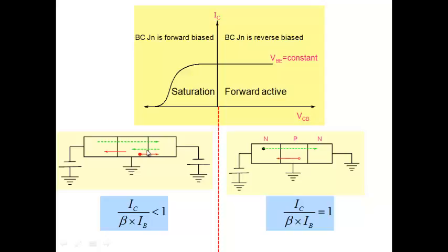So collector base junction is larger, it has lesser doping, and it has higher currents associated with it. So when you are saying when does this begin to occur, maybe it begins to occur when collector base voltage is, let's say, 0.5. It depends on how the transistor is constructed. But it's lower than the base emitter voltage. Okay, so this starts falling. We'll show you transistor characteristics later on, so you can see where it begins to fall. Okay.